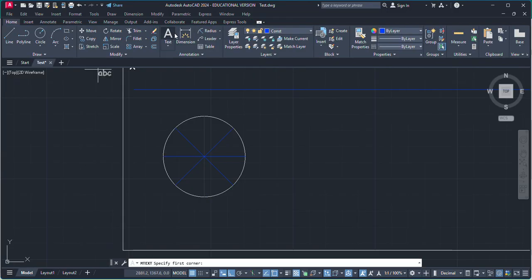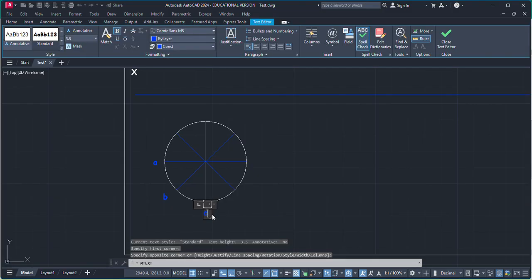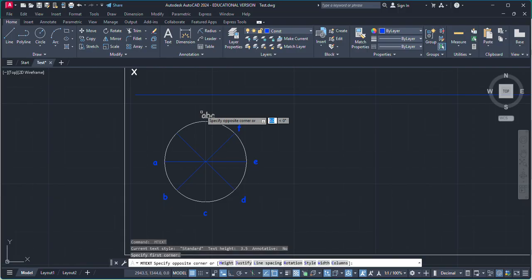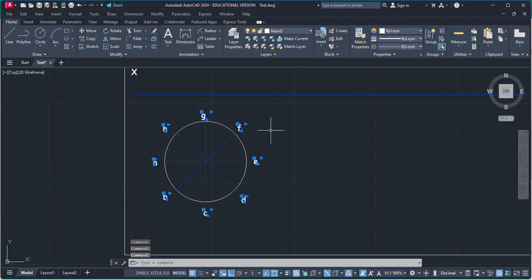Okay, now you can name these parts. Change it to main right now. While it is resting on the HP on one of its point, suppose this circular profile is resting on this point A, which is, as per the question, lying on its circumference. Now this is the top view. So from this top view we are going to draw our front view.